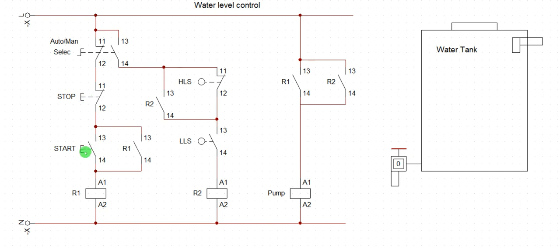Now this start button will be activated for us to have power to the relay, relay one. This relay has two contacts. This is one of the contacts and this is another contact. This contact is responsible for latching the relay to make it maintain power. That is why I call this logic the latching circuit, and it's our manual circuit. This one is our manual logic. Then here is our auto logic. Then this one is the power logic to send power to our pump.